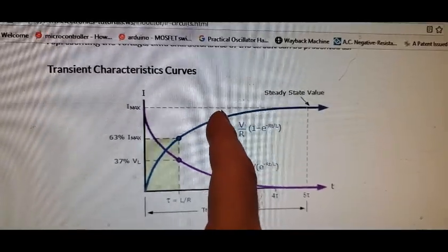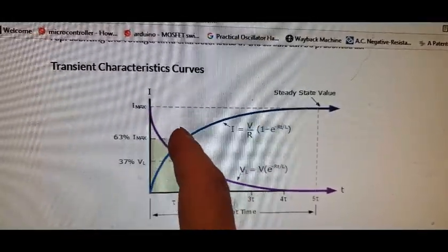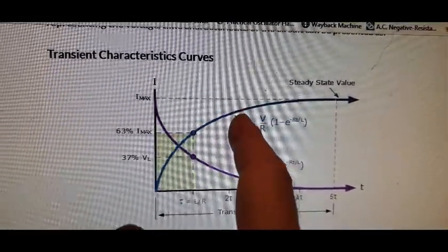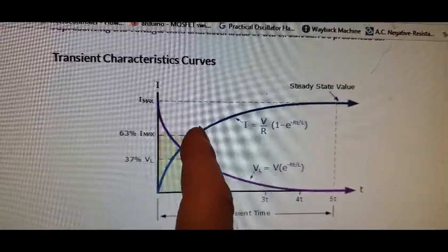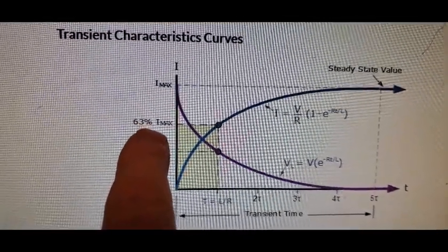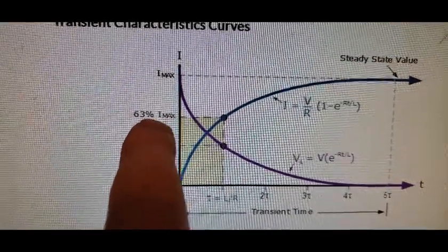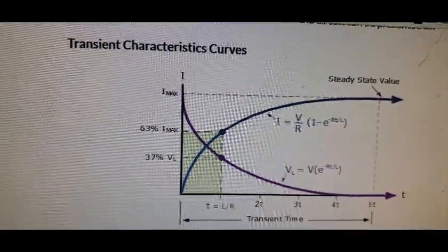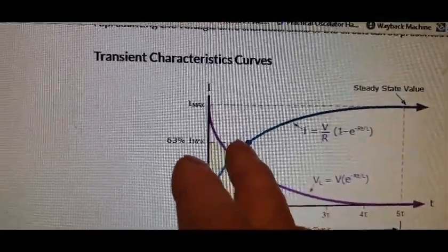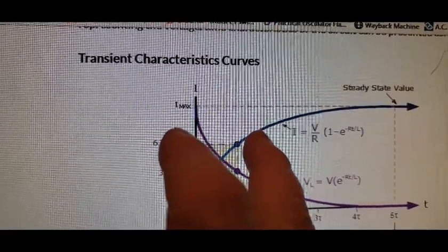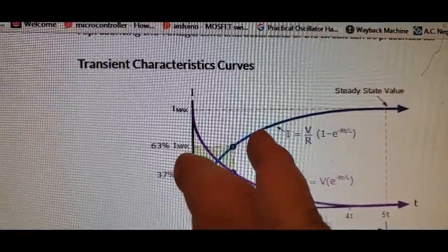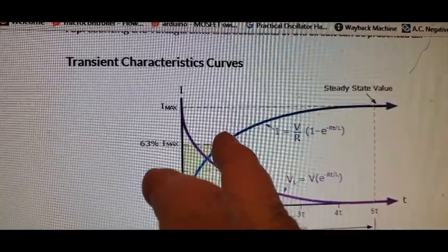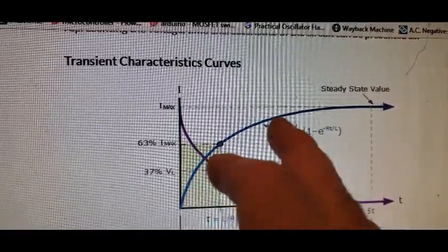And then what if you go from 2 to 1, and you can see you've used half as much charge, but you still have 63% of the magnetic field strength. I mean, actually, you've used less than half the charge in going from 2 to 1, because this part was a lower resistance part of the curve here.